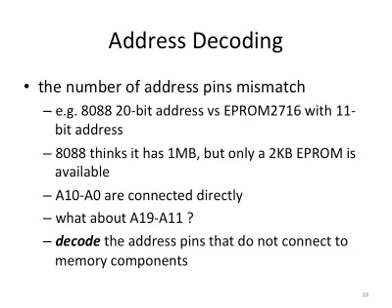So on one side, the microprocessor thinks that it has 1 megabyte of address space. It can access this large range. But on the other hand, if you have only this 2716 chip, it can only provide 2K of content for this microprocessor.